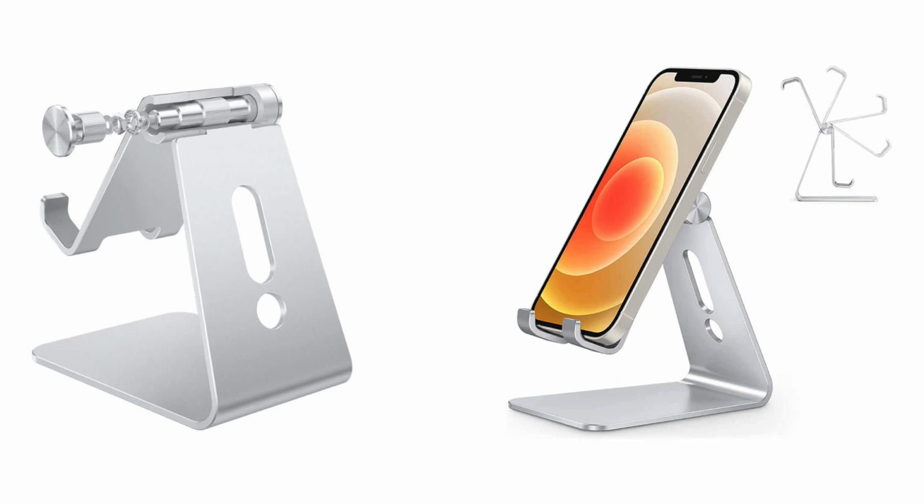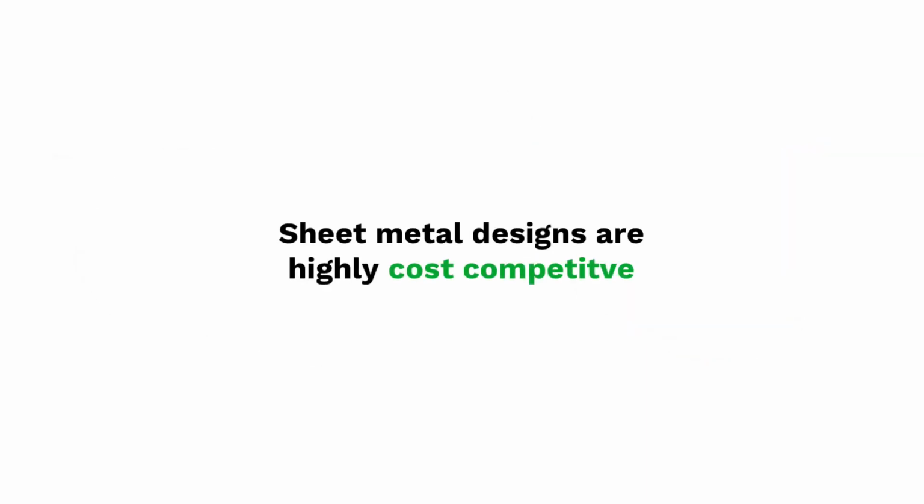And I'm not gonna linger on sheet metal any more than that, but I'm just gonna leave you with this key takeaway, which is that if your product can be envisioned in a type of metal origami design, then that is likely the most affordable option for manufacturing when balancing the startup cost and the per unit price.